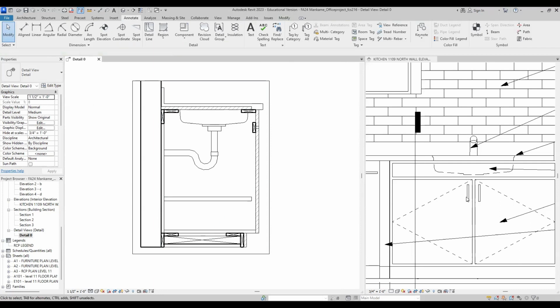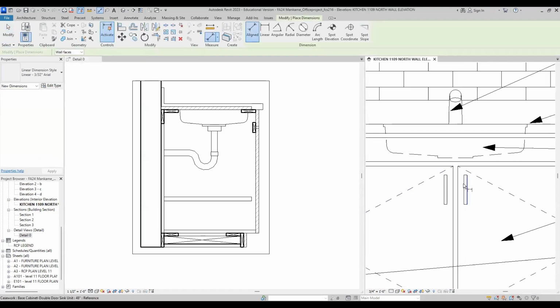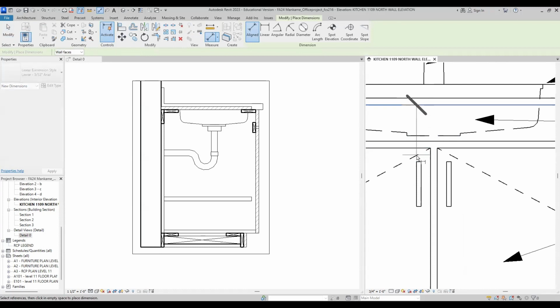And now if you see here, you have the handle in here. So we will add that handle. We just want to make sure that we are doing what we see in the elevation here in a detail section. So let me see how tall the handle is. We will just go back in here and check from the top, 6 1/4, and from here to here, 4 7/8.